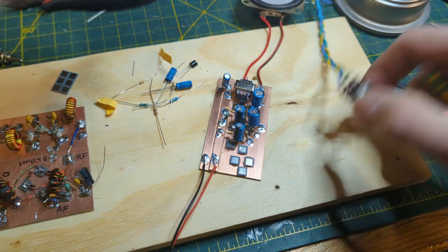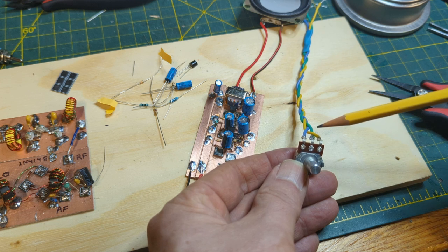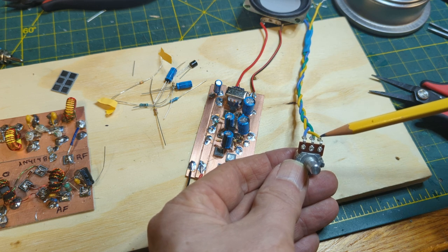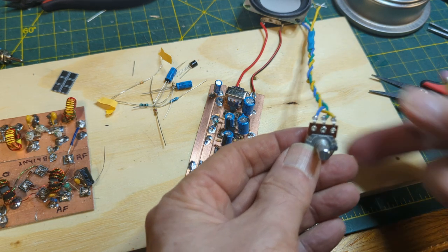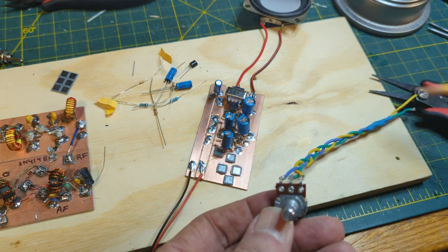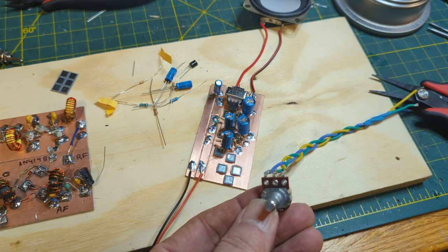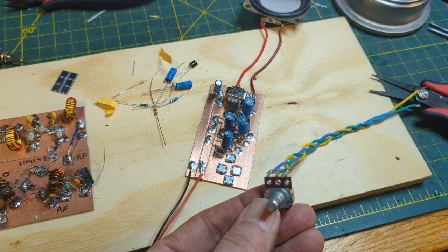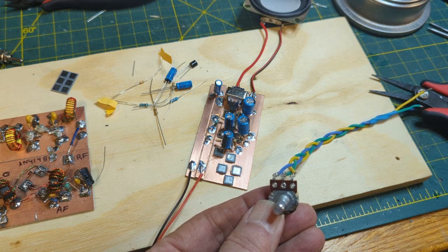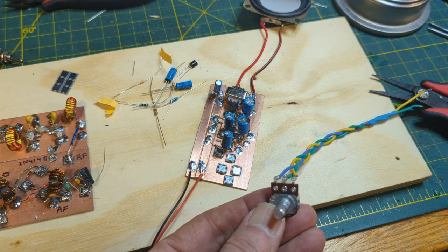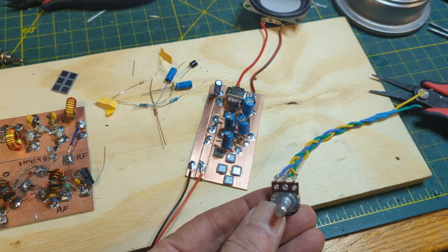When you look at the potentiometer, the center terminal is the wiper, and then I'm going to use this yellow wire to be the high side and the blue to be ground. The reason that they're braided is we want to keep noise off of these wires, and it's just like having a twisted pair. You can use other techniques to keep the noise off of the audio line. You could use shielded wire. You could twist the top 2 wires together and have a twisted pair and just run the ground to ground. But in any case, I do this just to keep the noise off of the wire. Many ways to deal with it.